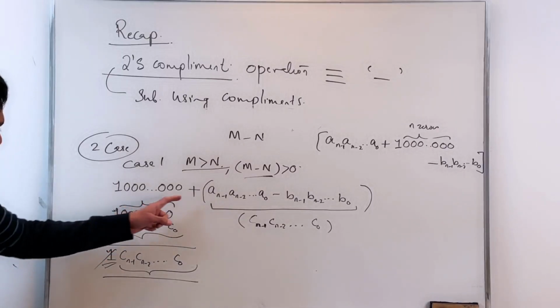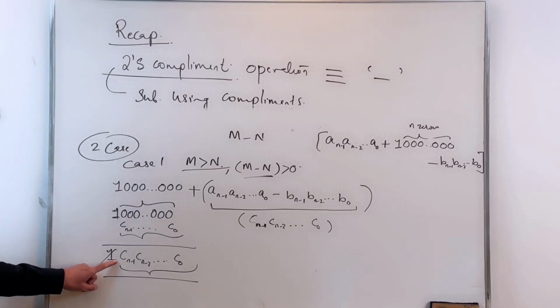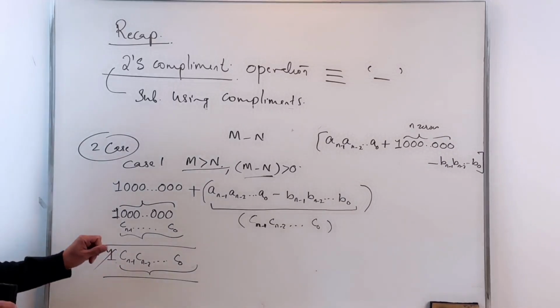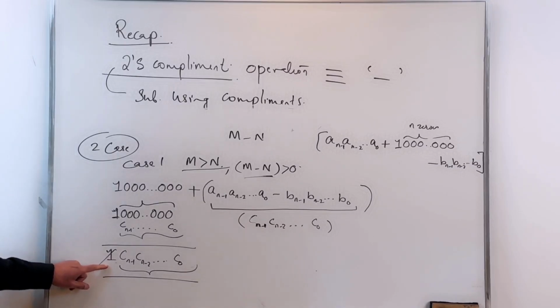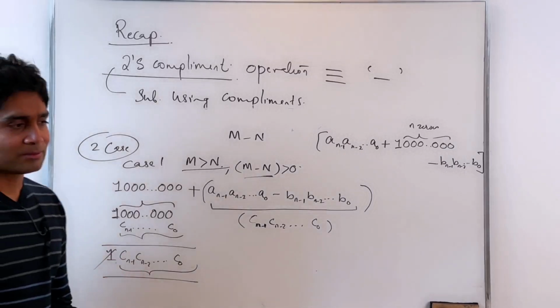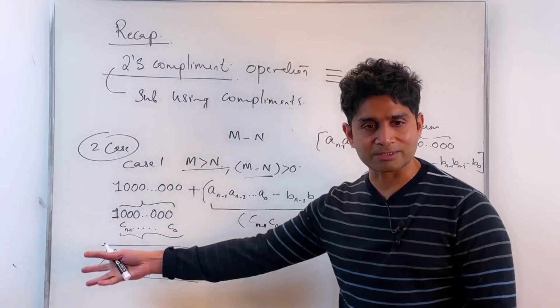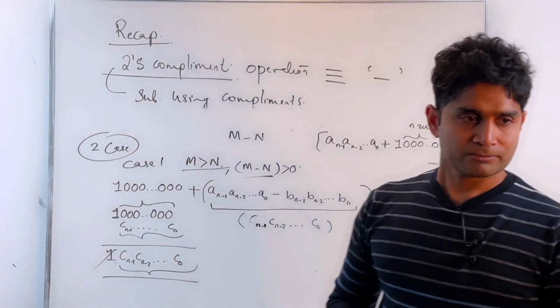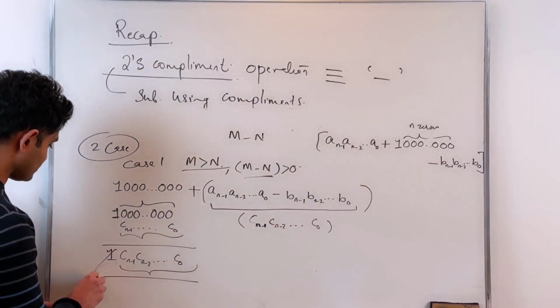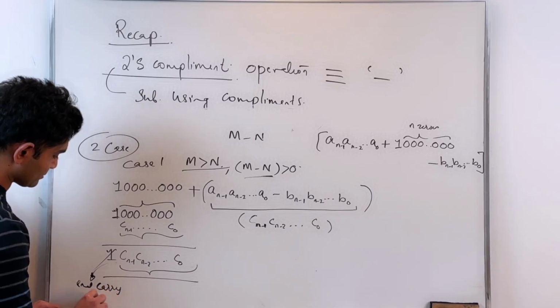Now when I'm doing the 2's complement subtraction approach, I also get an additional thing, we call that the end carry, this additional 1, which I really don't need because that's the answer. So I just discard that end carry. Discard it.